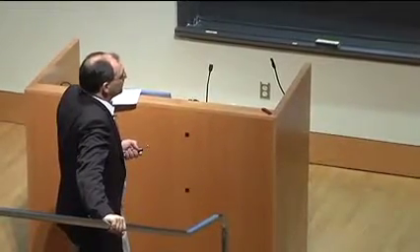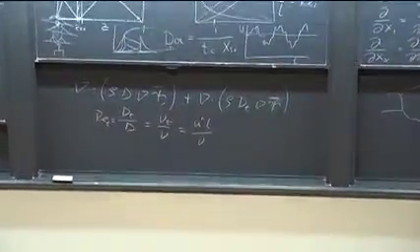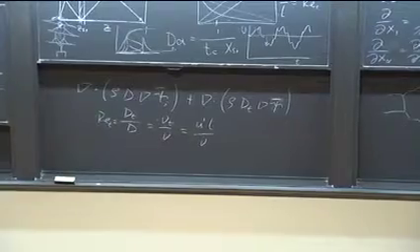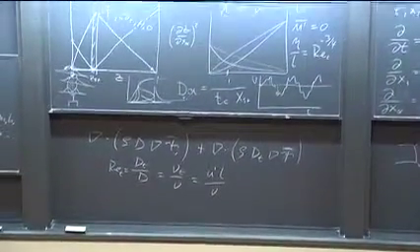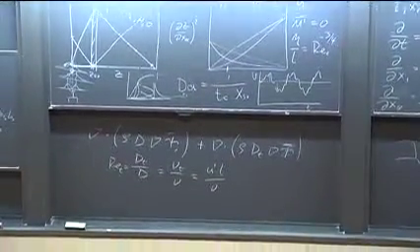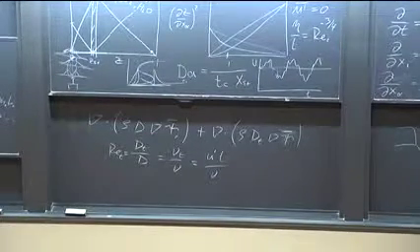We see for non-premixed combustion, this would also hold for other scalars. For premixed combustion, this assumption that we make here is actually not all that good. But again, I'm coming back to making the exact same assumption. This is the molecular flux, Fick's law. That's just a closure model that somebody introduced into this species transport equation.